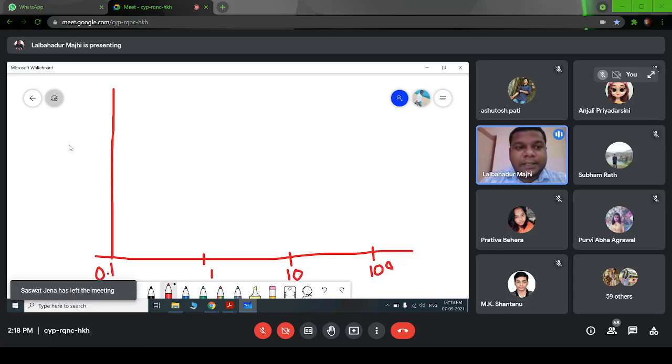So our first step is, it is a type 0 system. The starting point of our magnitude plot is 20 log K, which we have got as 60 dB. Okay, so we are getting only positive, so I am taking only the positive. So let me take also the negative one.